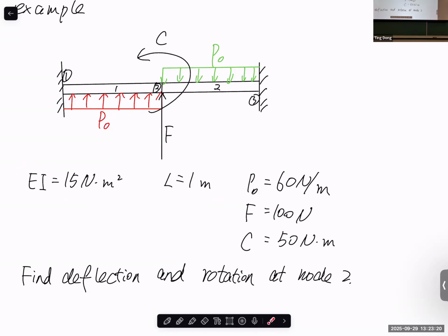Now for the K part, there's nothing tricky. EI and L are given, you have the original 4x4 for element 1, and 4x4 for element 2. Assembly, you should have 6x6. Applying the boundary condition, you have 2x2. That one is exactly the same as what we learned in the previous section. The thing directly connected with our content today is how to write the force vector in the KQ equals F matrix equation. We need to find the equivalent of the force first.